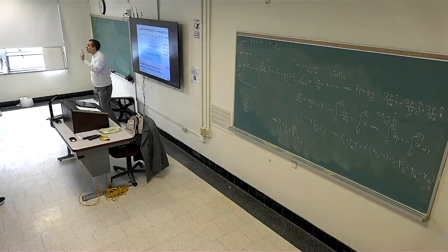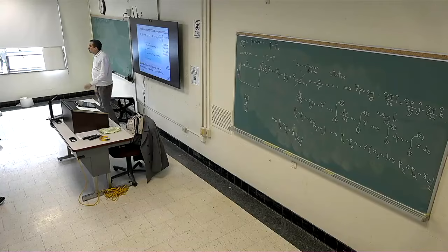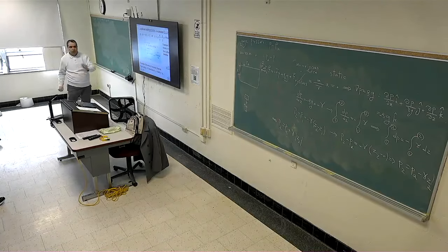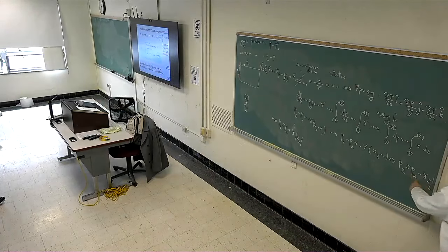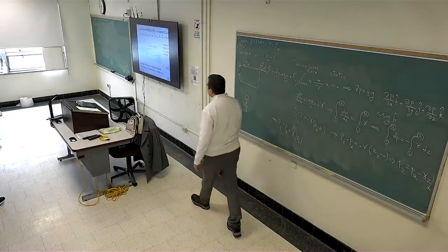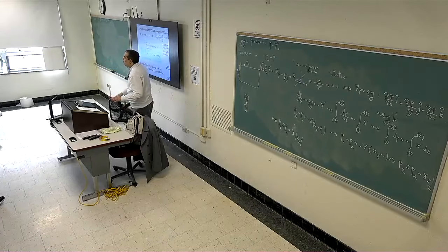Now, I have a submarine. My submarine moves at -h. There should be a large amount of pressure over my submarine. Why? From the equation, P2 is PA minus gamma Z2. For the submarine, Z2 is -h. Minus by minus is plus, so P2 is greater than P ambient. Super easy. If you go up, your pressure drops. If you go down, your pressure increases.